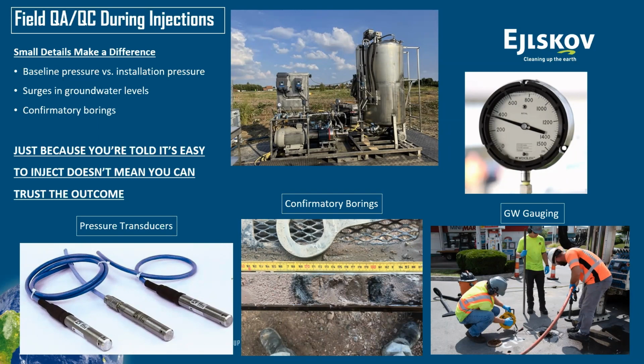On the groundwater side of things, there are little tricks that could be used in the field by, for example, installing pressure transducers in the wells, or performing just manual groundwater gauging, or stop for a day, do a few confirmatory borings as well to just check presence of the product. And that allows you to go through the installation period with a little bit more confidence, so that by the time you're done with the installation, you already have a sense of what you have done and what you could expect out of your future groundwater data.